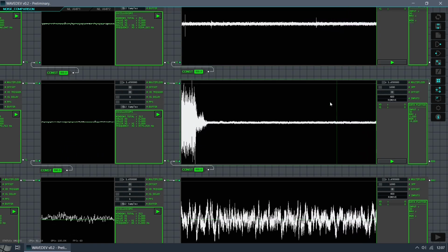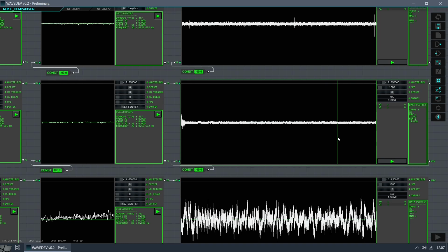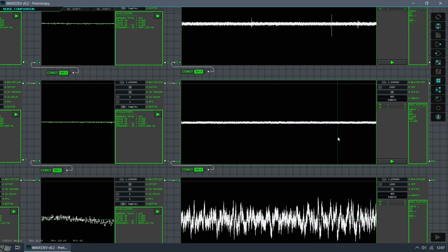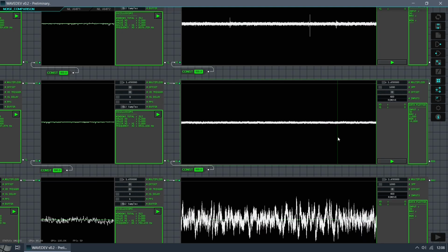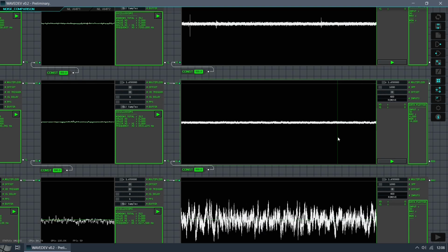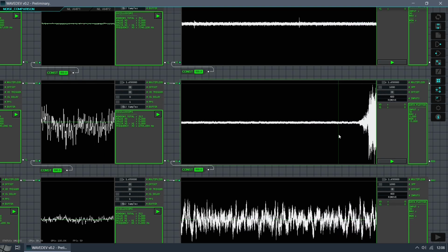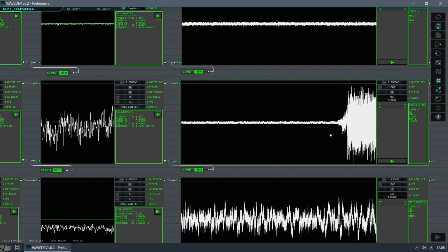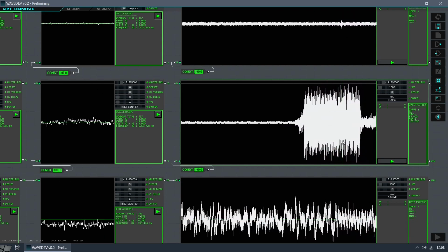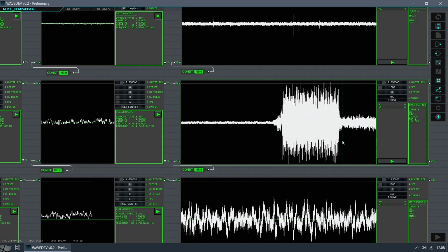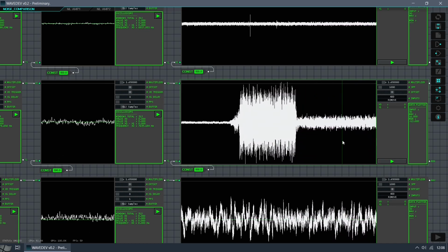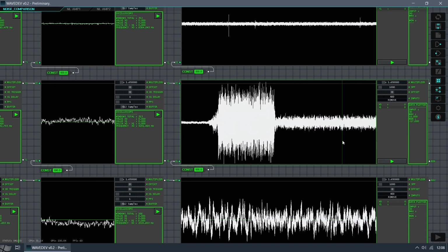But right now the sample here is so small that we are wasting dynamic range of the converter. And this means lower resolution sample, therefore lower signal quality. Now, I cannot state that all audio interfaces are this noisy. But let's assume this is the worst case. Most interfaces are still generic, and I don't recommend connecting an electric guitar directly to a generic interface due to impedance issues.